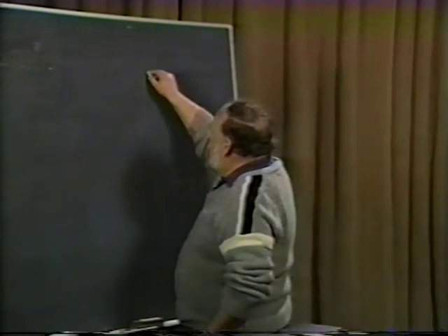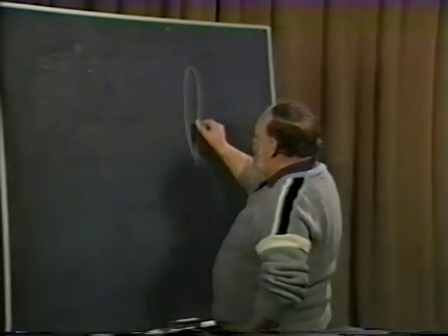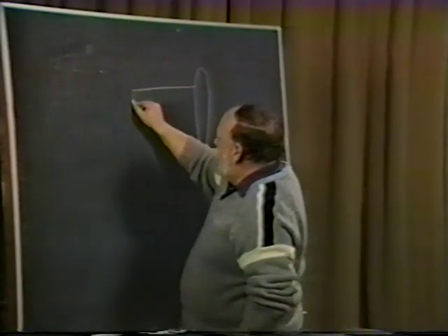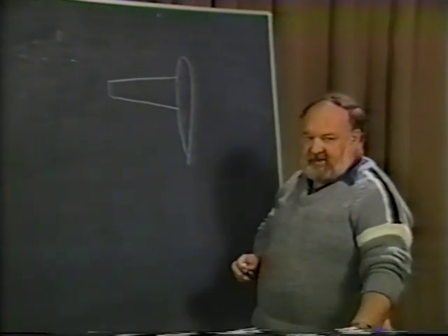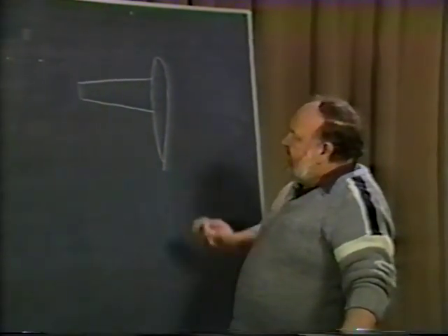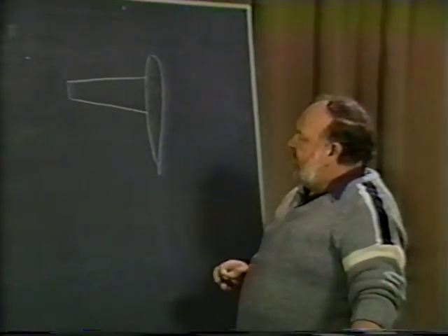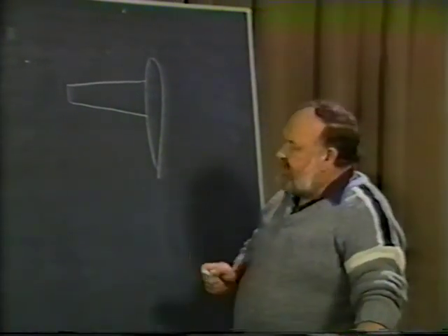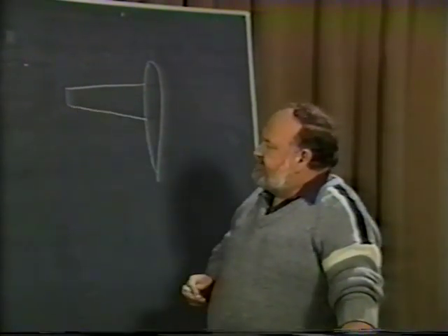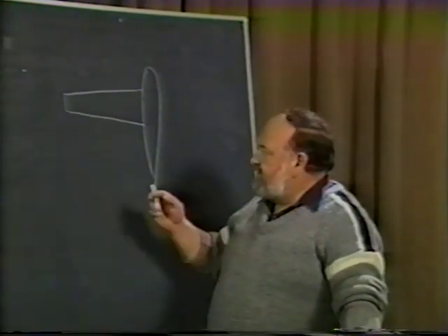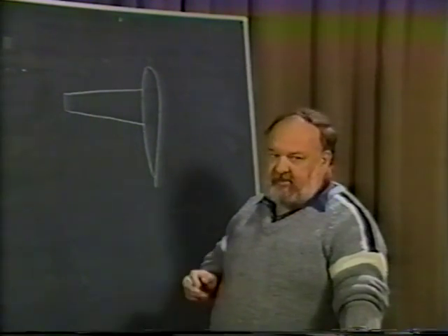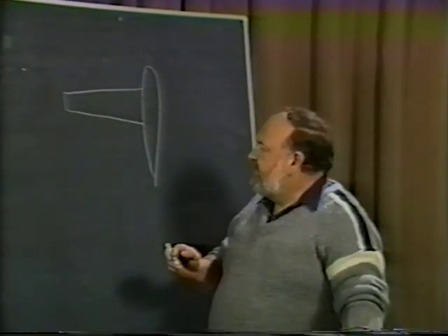Let's take a look at the basic wing plan form of a normal general aviation airplane. This would be a top view. We might look at a tapered wing section. This is somewhat of a standard type of design you see on an awful lot of airplanes. Fundamentally, this plan form here is quite good, except for maybe one possibility, and that is that the tapered section tends to give us a lower Reynolds number on that airfoil section, and the lower the Reynolds number, generally, the more adverse the stall pattern might be on that particular aircraft.